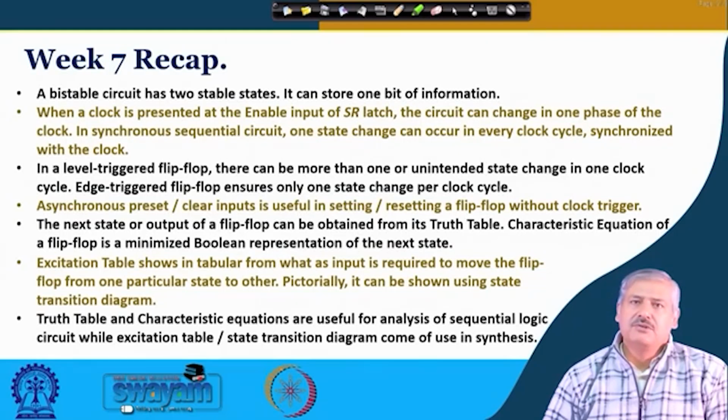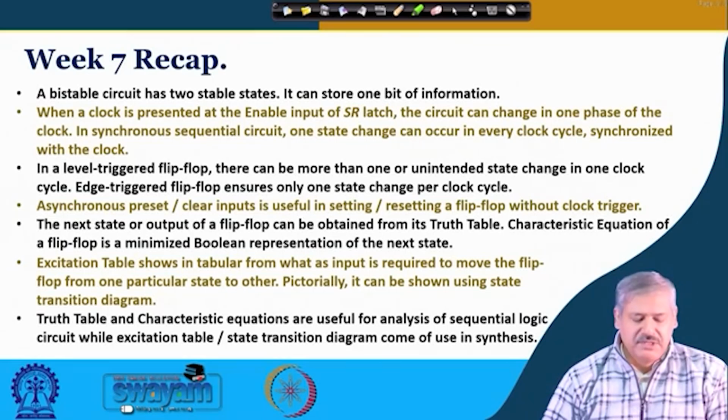And we also studied asynchronous preset and clear input, how it performs and how it changes the output or the state without requirement of a clock trigger, and which is useful for initialization and various kind of resetting purposes.